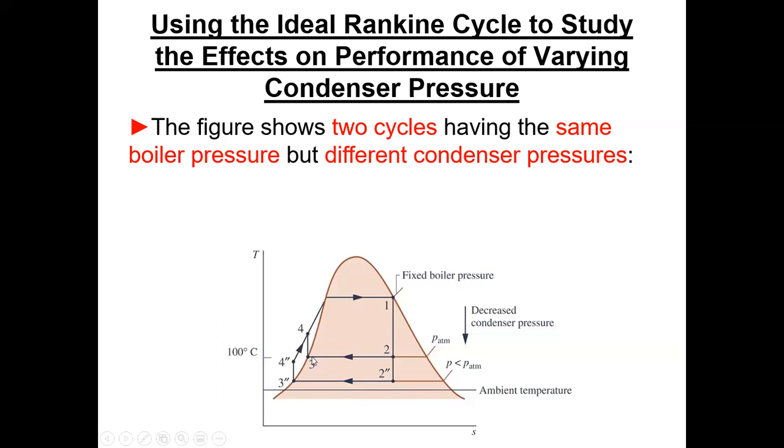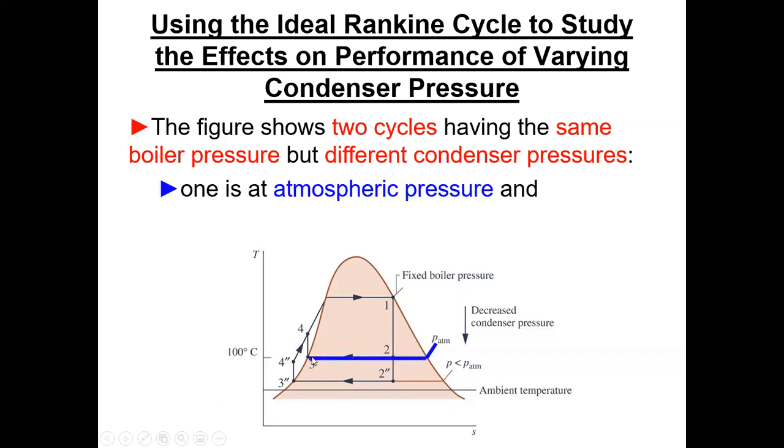So the amount of moisture in the turbine is increasing, and that's hurting my turbine. It's helping my efficiency, so I'm getting a little more work out per unit of fuel input. That's the way these changes come, with pluses and minuses. Then we have to figure out other things we can do to get rid of some of the minuses, keep the pluses and moderate the minuses.